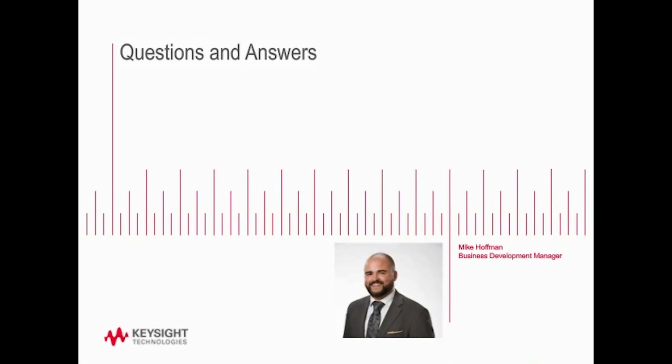Okay, here's another one where you have to figure out the balance. When would you use a counter to measure frequency versus using the frequency measurement support? Good question. If you're using the measurement function, the signal needs to be on screen, scaled properly, stable and triggered. The counter doesn't necessarily need that. It's like a standalone counter on your benchtop where there's no trigger setting. It just works.